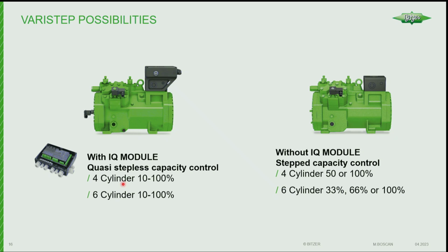So up until now, for CO2 compressors, your only choice for capacity regulation was a VFD because there was no mechanical unloading. So with the TE series, we introduced mechanical unloading. Now you have a choice of VFD, but you wouldn't do both. You can't do both. You don't have enough mass flow if you go over the motor if you do both. But you could do both on a rack. Compressor 1 could have a VFD, Compressor 2 could have mechanical unloading, and that way you can get better staging. Or you can do 2 with mechanical unloading, a 4 and a 6 cylinder. Now you have a bunch of steps, but they can be used both on the same rack, but not on the same compressor.